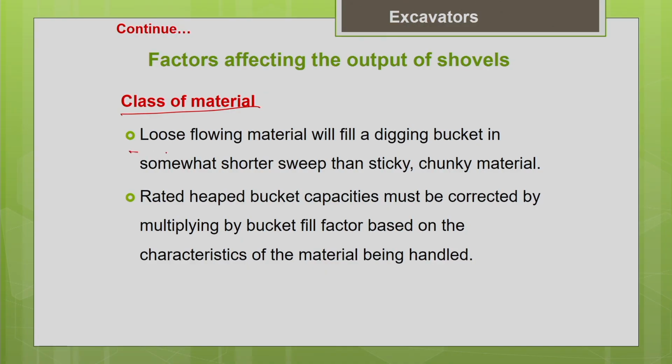So it depends upon the flowing ability of the material. So that is going to affect the cycle time and the productivity of your machine. Loose flowing material will fill the digging bucket in somewhat shorter sweep than sticky and chunky material. And another important thing you already know is just like what we discussed for the loaders, here also we can get the rated heaped bucket capacity from the manufacturer.